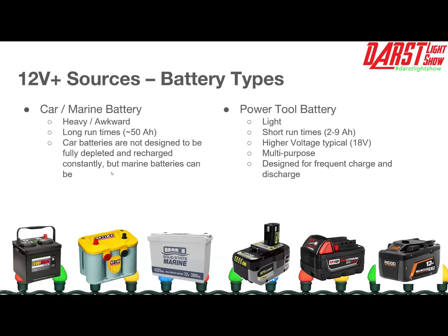Something to keep in mind with these is marine batteries are usually a good choice here because car batteries are not designed to be fully depleted and recharged over and over, where marine batteries are. So you're going to get a lot more life out of a marine battery if you're actually running it down to zero, charging it back up, running it down to zero. But then that might be your only use for it, where with a car battery, you might be able to get multiple uses out of it. Okay. So just something to keep in mind. These are heavy, they're large, so you don't want to throw them in a backpack.